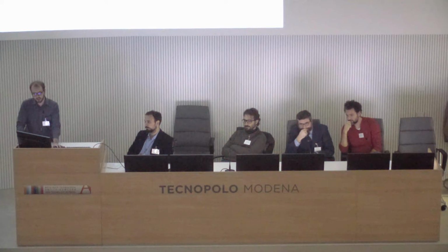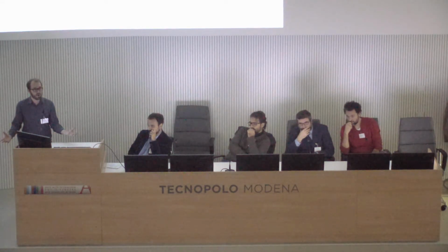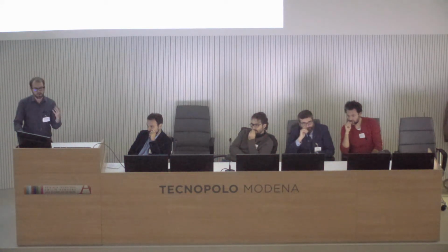In order to do that, we developed a specific constitutive equation, which is something that is not available in all finite element codes. So we have the mFront interface, which is a little software that is included within Code-aster, also open source, in which you can easily write constitutive equations. Basically, if you know the equations, you just have to write them, and then Code-aster will be able to read them. It's a specific language oriented toward differential equations, I would say.